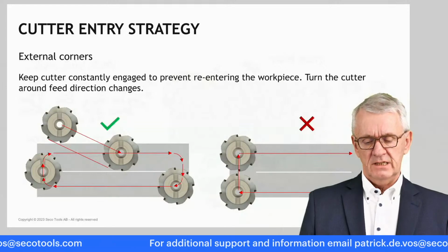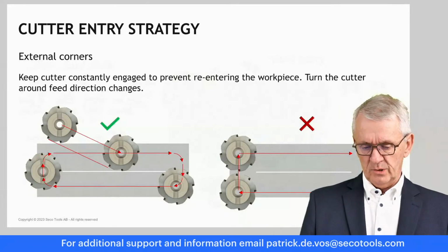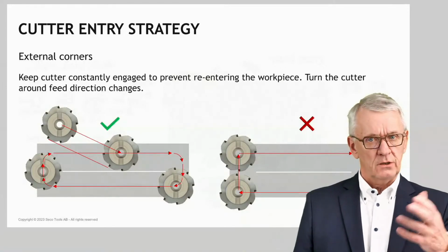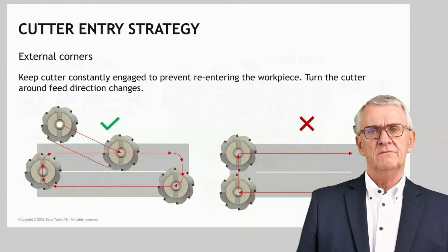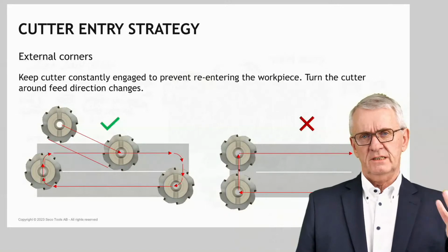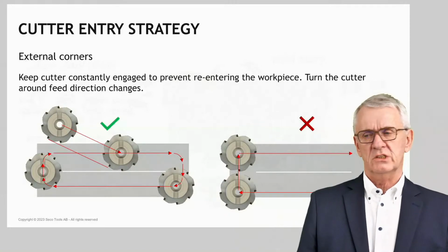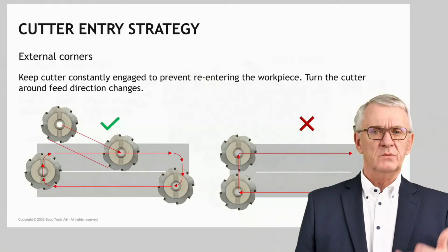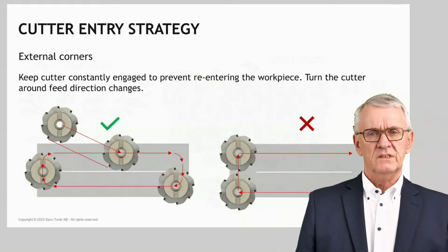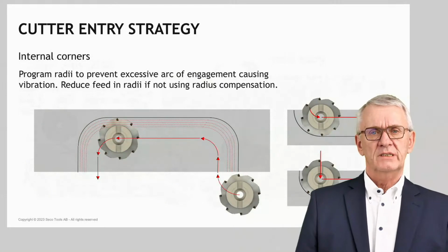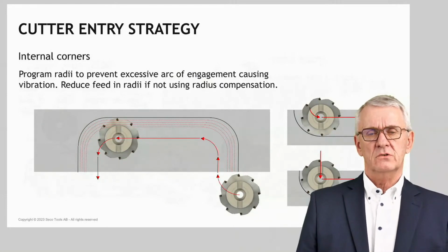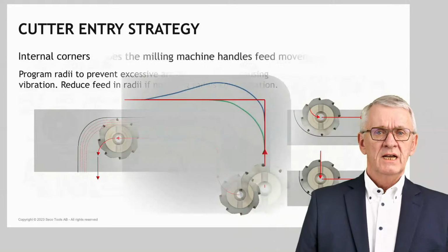In other cases, I think mainly when you have milling operations in stainless steel, superalloys, or milling operations in forged workpieces with very difficult to machine skins, the state of the machine you use, all of these are the critical factors that decide should you spend a lot of attention to this or not so much attention.